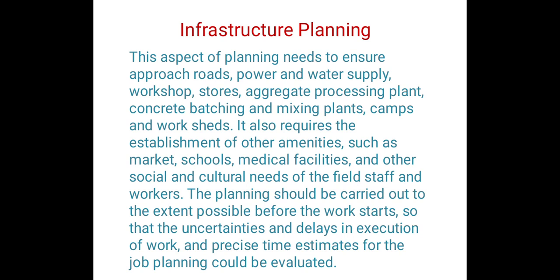First one is infrastructure planning. This aspect of planning needs to ensure approach roads, power and water supply, workshops, stores, aggregate processing plant, concrete batching and mixing plants, camps and work sheds. It also requires the establishment of other amenities such as market, schools, medical facilities and other social and cultural needs of the field staff and workers. The planning should be carried out to the extent possible before the work starts so that the uncertainties and delays in execution of work and precise time estimates for the job planning could be evaluated.